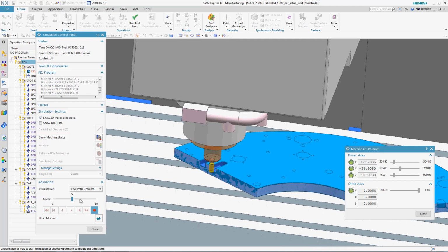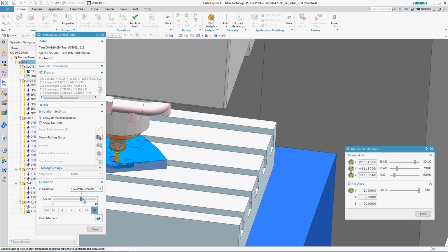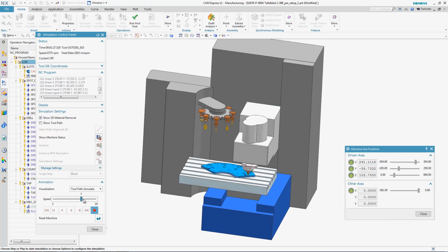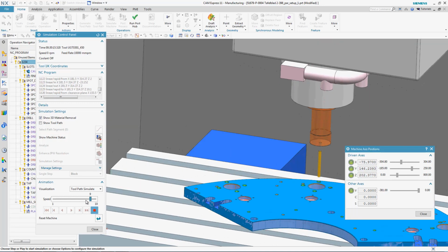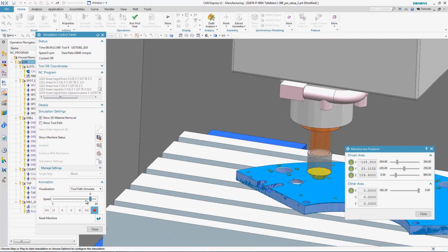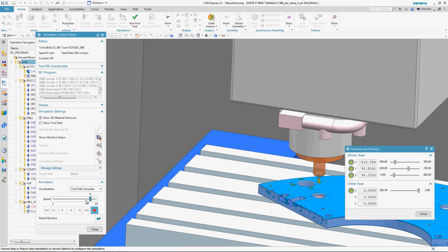Once the full machining process is created, a G-code simulation shows the full operation taking place exactly as it would in the machine shop. This example requires a relatively simple 2.5-axis machining operation, but 3, 4, and even 5-axis machining operations are supported to manufacture more complex components.